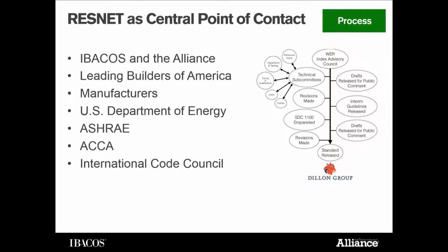Will there be a different comfort level in the summer to winter due to the amount of clothing? I find this personally, and I think that makes perfect sense, due to the amount of clothing people are used to wearing. So the set point you might have in the winter is different than the summer. So more clothes in the winter make you comfortable at lower temperatures? Yes, correct. So what do you guys think about that?